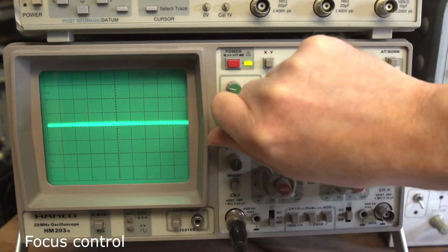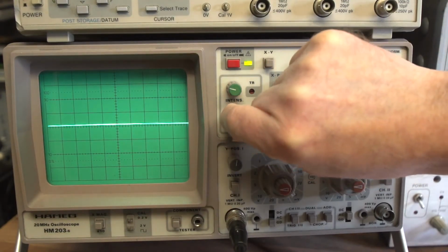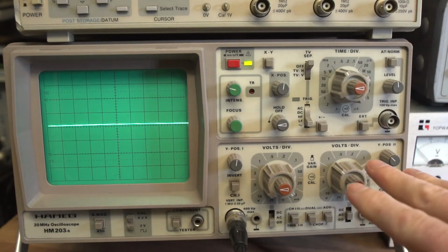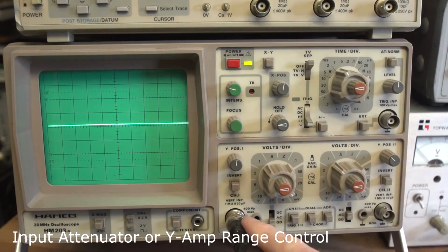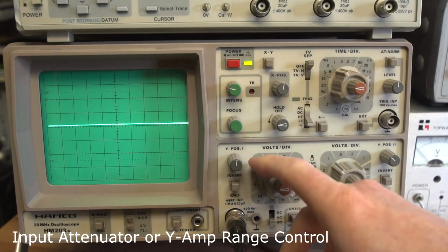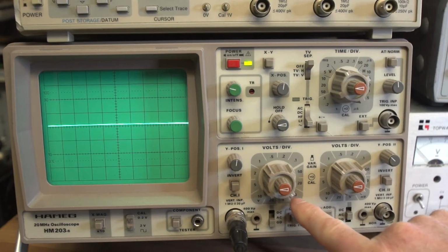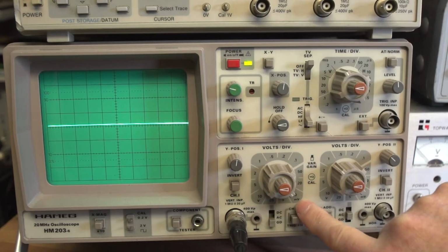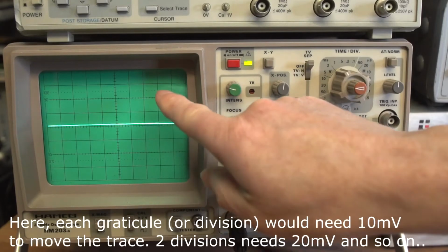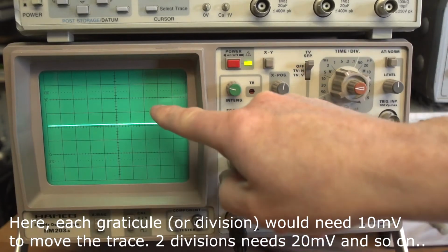You have a focus control, pretty much does what it says on the tin. You adjust that to get as sharp a display as possible. The main controls here are those and the input attenuator. When the signal comes in through the BNC socket here, you can adjust the sensitivity of the signal. You can either look at it in terms of volts or millivolts. And if you have the control set like it is right now, it's set to the 10 millivolt position. And what that means is, for every 1 centimeter or graticule position on the screen, it takes 10 millivolts to move the line either positive or negative.